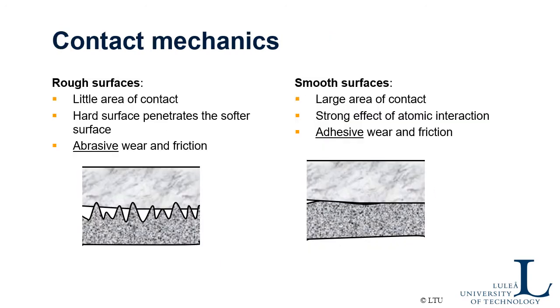I also want to remind you about the contact mechanics. There is a difference between rough surface contacts and smooth surface contact. If you have a rough surface, there is a smaller area of contact, or smaller real area of contact, so the actual place where the asperities touch the other surface. And if this one, the rough surface, is hard, then it will penetrate into this softer surface.